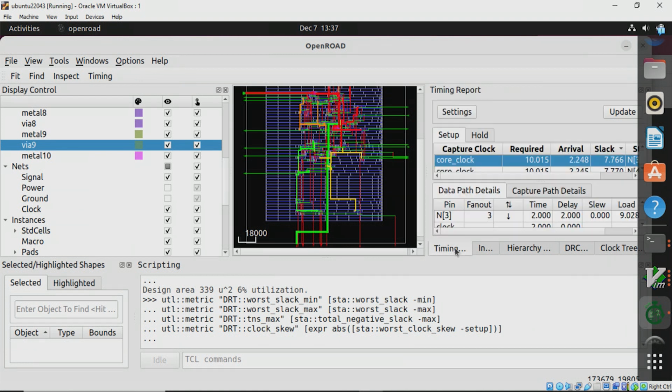Then also you can see the timing report in a graphical format. So, you can check the timing reports one by one by clicking on them. Okay. So, like that you go one clock at a time. You can change that, and the corresponding signals you can also check online. If you can see here, the signals are also changing.